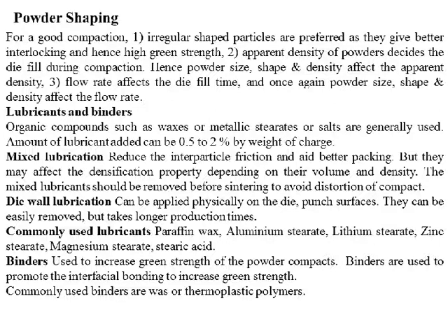The next topic is lubricants and binders. As we know, the powders used in preparation of a powder metallurgy component are mixed; two or three metallic powders are mixed. To these powders we add some lubricants. Why are these lubricants added? These lubricants are added in order to improve the binding property between the particles, and they try to reduce the friction between the die wall and the powder particles.